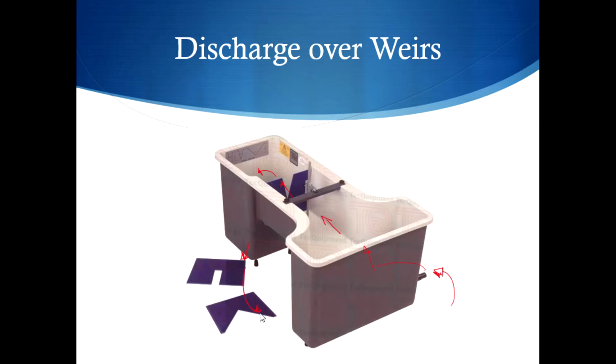Water is distributed evenly in the large tank. That leads to a short channel at the end of which there is a sealed groove where the weirs are attached. After the water reaches the weir, it flows over and is collected in the exit tank, which is this one. In order to measure the head of the water before the weir, that is to say upstream, we will have a point gauge, which is this instrument, with which we will calculate the head of the flow.